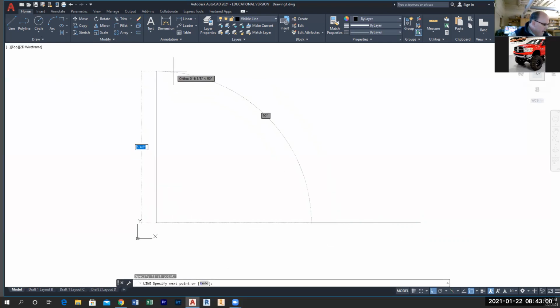And how high? The height of my front view is 1.5 inches. The depth of my top view is 2.5 inches, plus about 1 inch or maybe 1.5 inches in between views. Whatever it is, it should be the same: 1.5 inches in between views, both the front and the top, and the front and the right side, or 1 inch between the front and the top, or 1 inch between the front and right side. Whatever it is, it should be even. Okay, so here I go. The overall height is 1.5 plus maybe let's just say 1 inch. So that's 2.5 plus 2.5 is 5 inches.